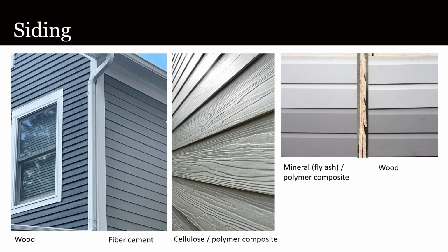Both of the widely available substitute materials are thinner than any traditional wood siding, and the thicker version of cement board is an option that's too thick to accurately replicate traditional wood siding that was used for the narrow exposure, such as 4 inches. When the thickness differential of the substitutes is discernible, it limits them to use on very secondary elevations or new additions.